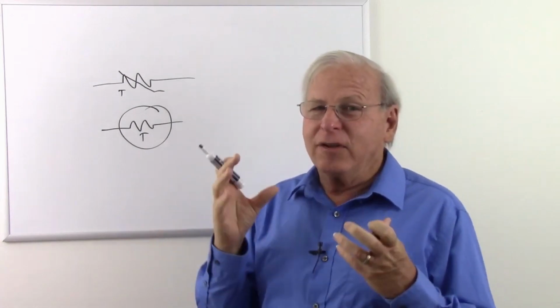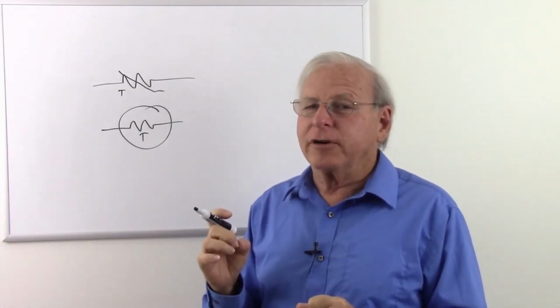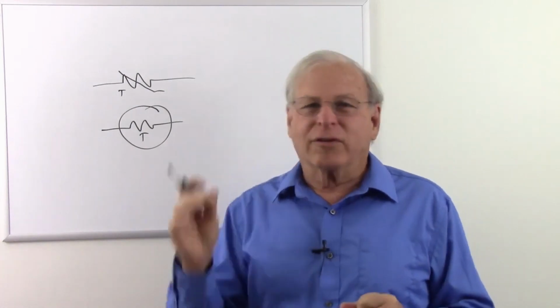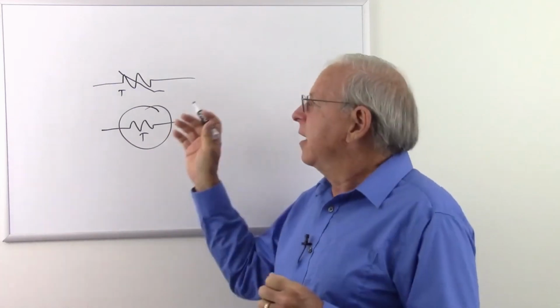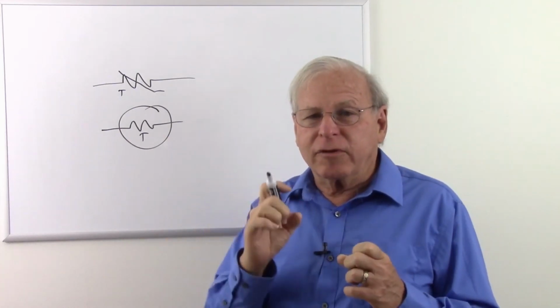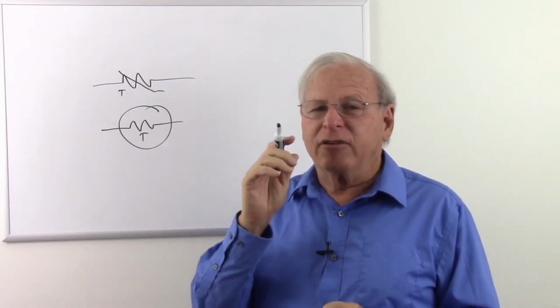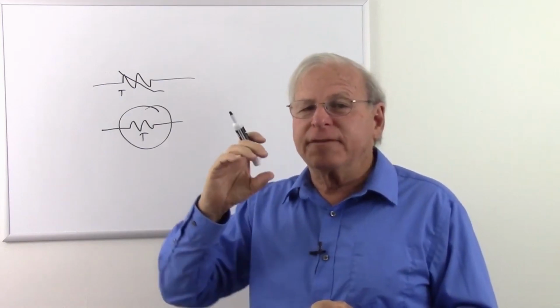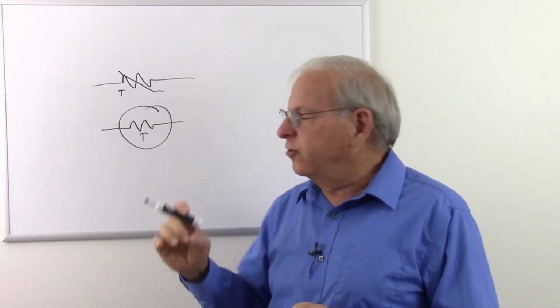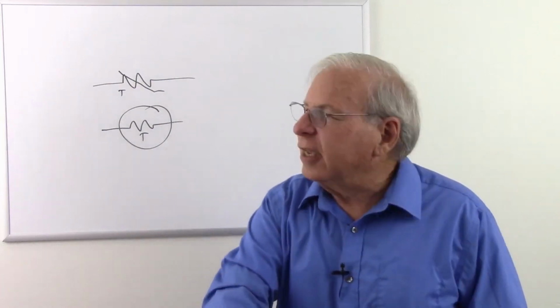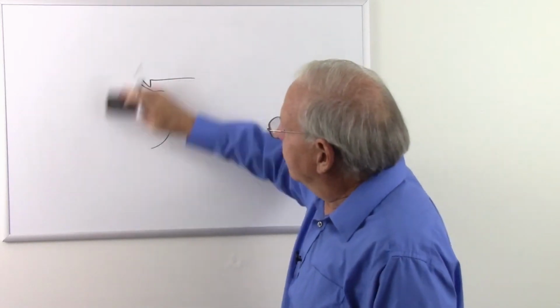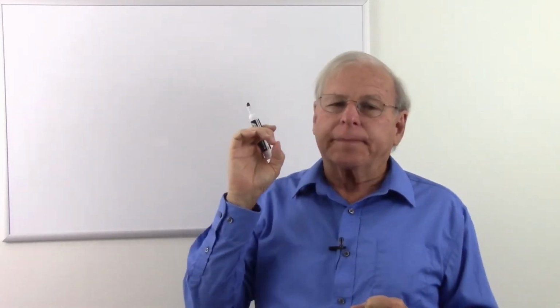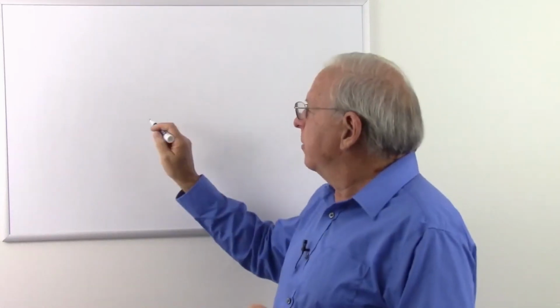Thermistor. So it's a resistor that is sensitive to temperature. Except all resistors are sensitive to temperature. Well, thermistors are resistors that are manufactured to have a certain coefficient of resistance based on temperature. So it's a known quantity and it's manufactured such to have a rather dramatic response to changes in temperature.